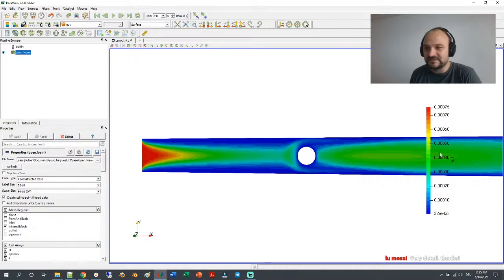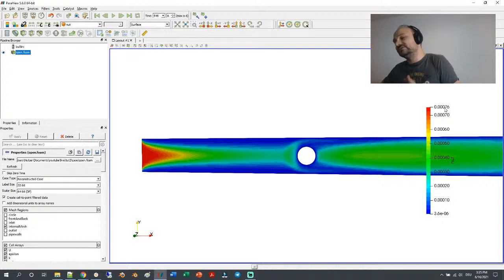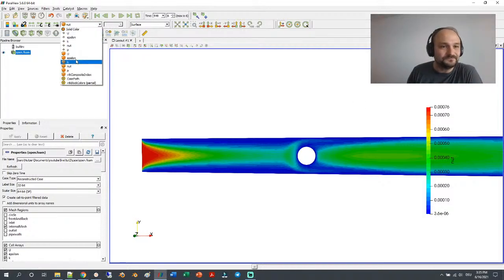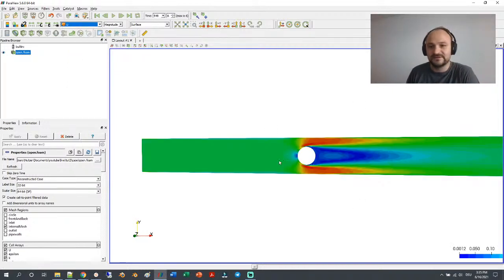So what do we see here? That is that the nu t value is 10 to the power of minus 4, or physical nu value of 10 to the power of minus 6 is at least 2 orders of magnitudes lower, which means that our flow is fully turbulent. So that's nice. Okay, so there is the velocity field.